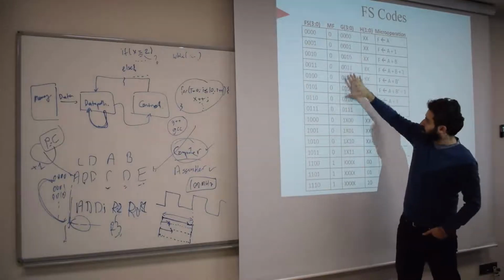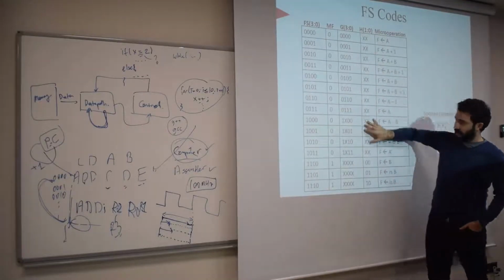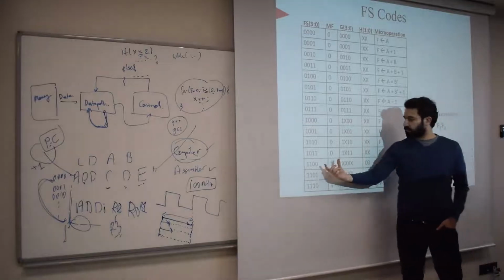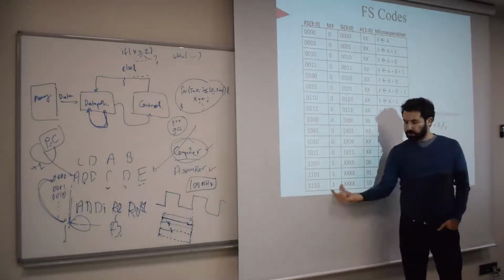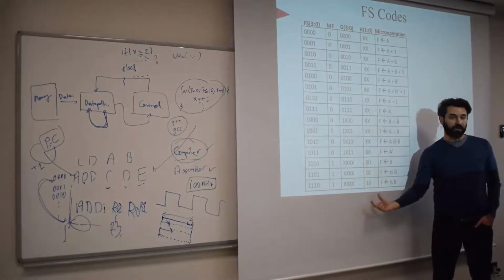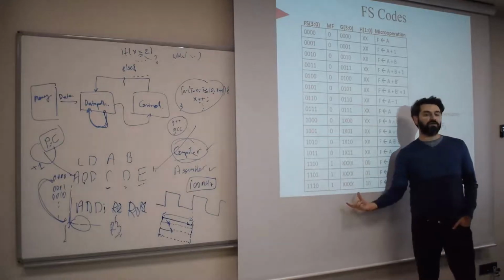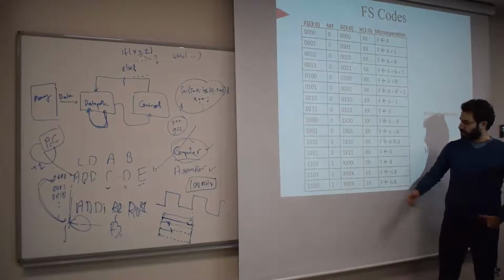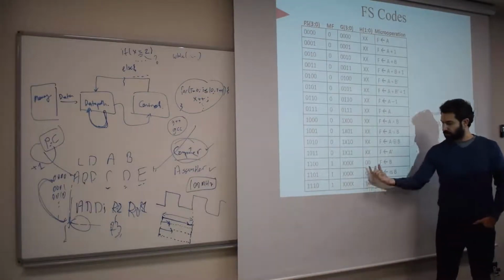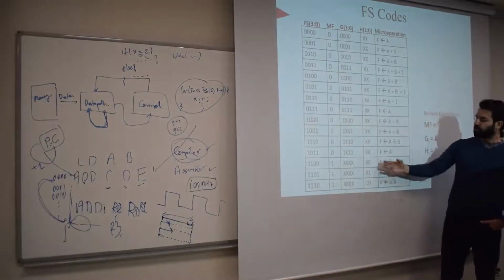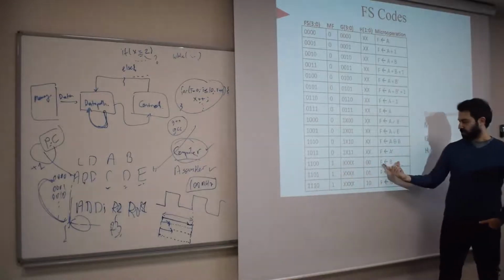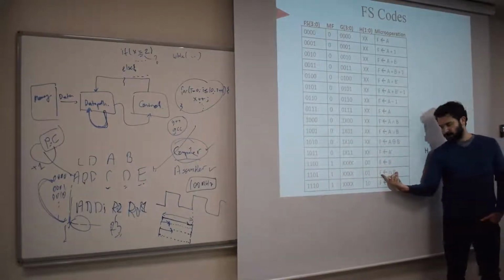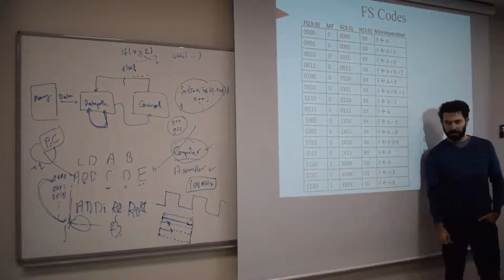That's why we have all these bits here, and don't cares for the H. And for MF equals 1, we have the shifter operating and the ALU disabled. So that's why we have those don't cares for the G input, and 0, 0, 0, 1, and 1, 0 for H to be able to select the right operations: copy operation, right shift by 1 bit, and left shift by 1 bit.